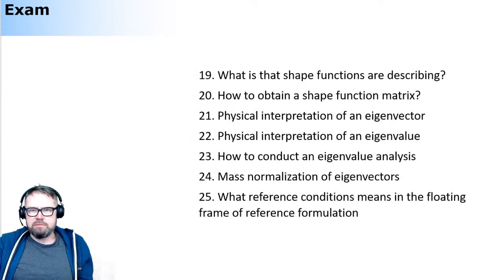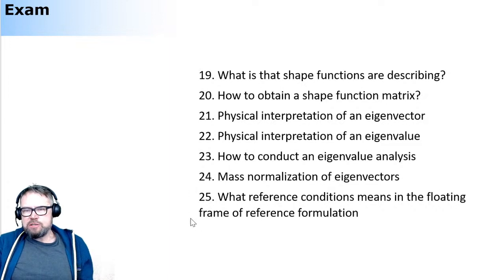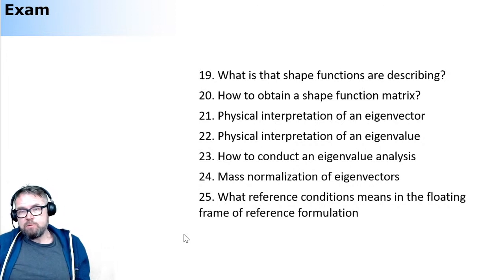And more, what the shape functions are describing, how to obtain the shape function matrix, physical interpretation of eigenvectors, eigenvalue, how to conduct an eigenvalue analysis, mass normalization. What the reference condition means in a floating frame reference coordinate formulation. And the reference condition means how do you set the boundary condition when you're defining these modes. That's what it is.